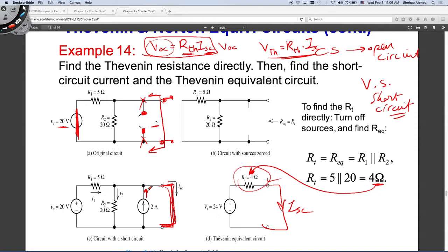If I look at the fluid analogy, it's the same. You have constant pressure pumps, and you have constant flow rate pumps. A constant flow rate pump requires pressure. If you have no impedance to the flow, the pressure internally in the pump will be low. But if you have impedance to the flow, to maintain the same flow rate, the pump will have to raise its pressure.